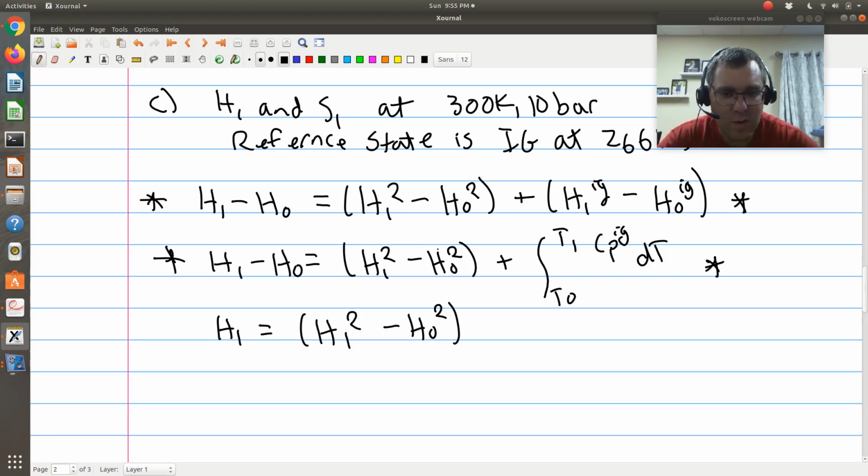As an aside, why I like this expression is that if I know the temperature and pressure of my state of interest and reference state, I can readily calculate the residual contributions from our MATLAB calculator, and this ideal gas term can readily be calculated. In general, we have polynomial expressions for this; you can look at the back of your book. Or in this problem, we're told that Cp is just constant. But the key is this ideal gas term can readily be calculated.